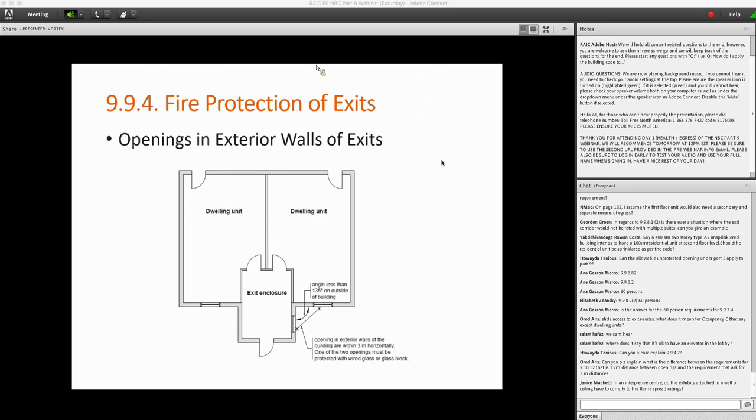So the requirement is that you locate it at 1 meter above the finished floor, so that will meet the exemption requirements for not requiring a guard, because the window sill is located more than 450 millimeters above the finished floor on one side of the window. Again, this is in 9.8.8.1 sentence 5.